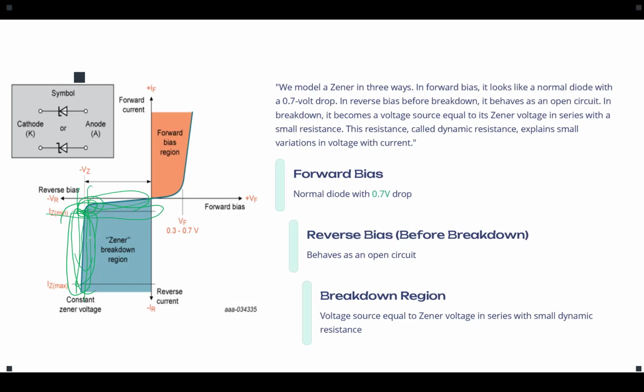When I say above, it's negative current, so value-wise, the value should be more than the minimum amount of current that you need to escape from that exponential part of the curve and go to the perfect linear vertical part of the reverse bias curve. Are we good?